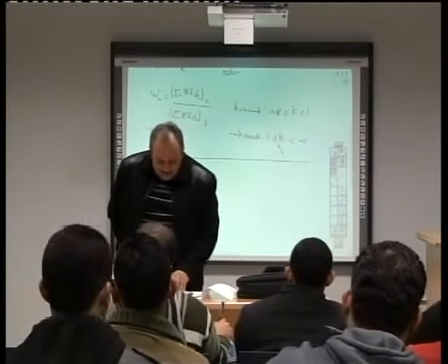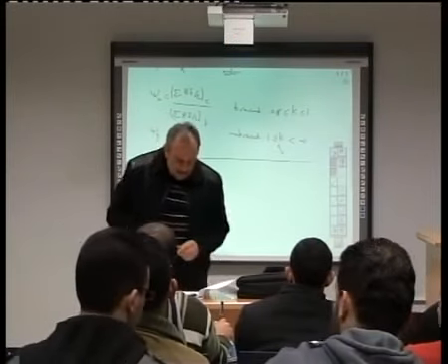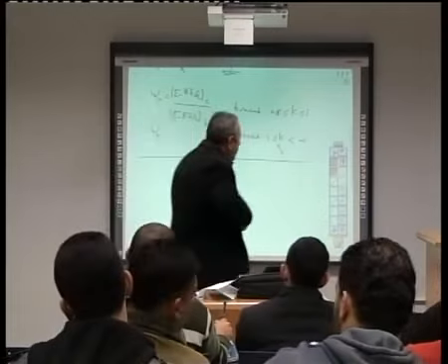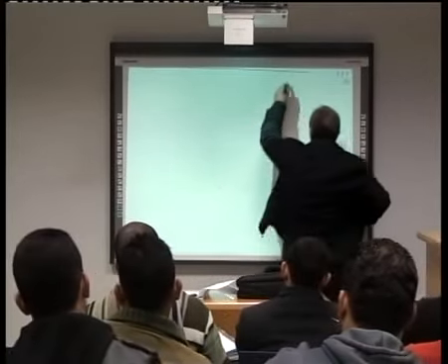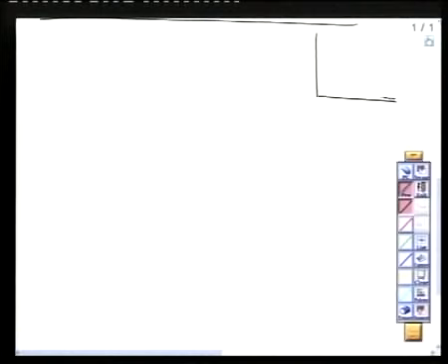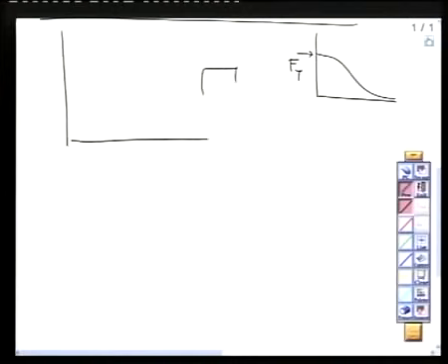Now, the third thing that we want to speak about is local buckling. In local buckling, we said, since the maximum stress that we approach in compression members is Fy, local buckling, if we took a plate, subject this plate to compression, then the stress-strain diagram will be something like this. The asymptote will be Fy.